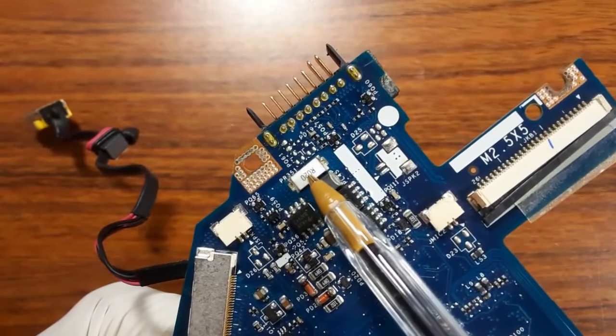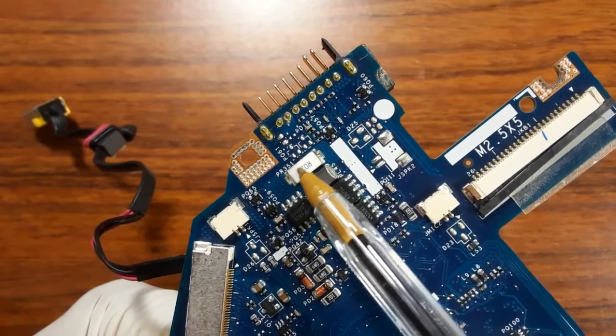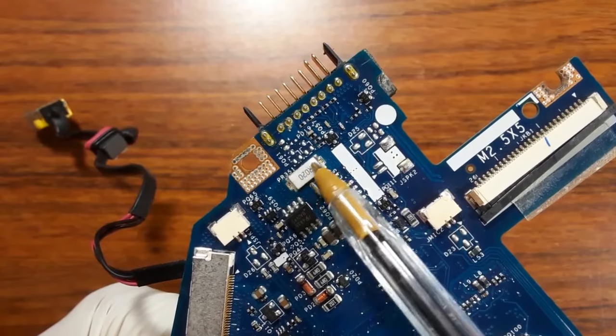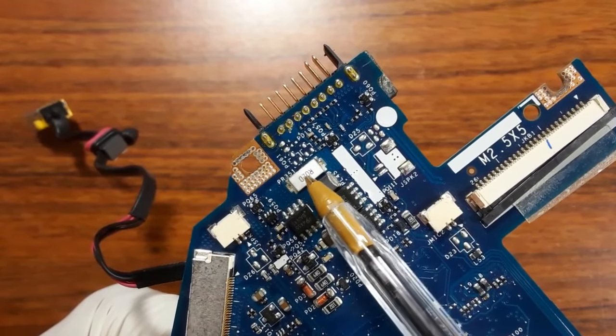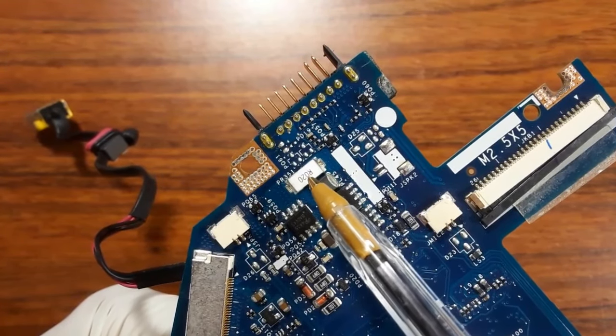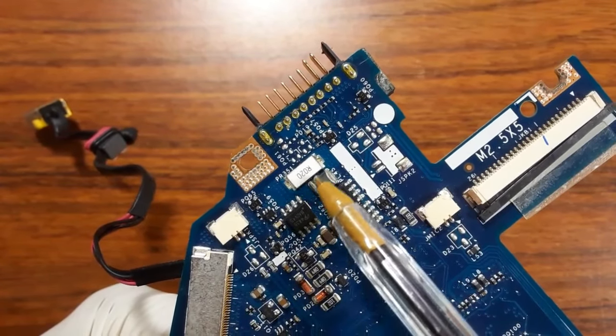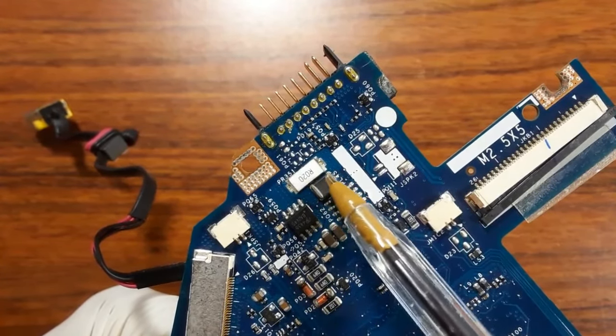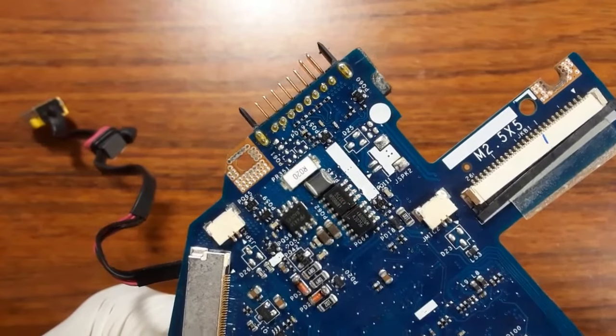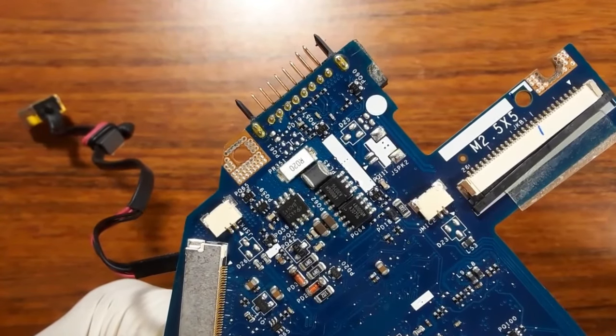As you can see here, this is a resistor, a current sense resistor. This should give a continuity. If it doesn't give a continuity or a buzzer, means it has failed. Here we have a coil. This is coil, not capacitor. Here we have MOSFET. So this is the main working principle.